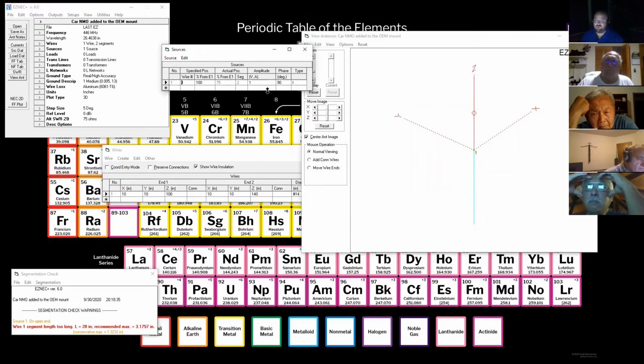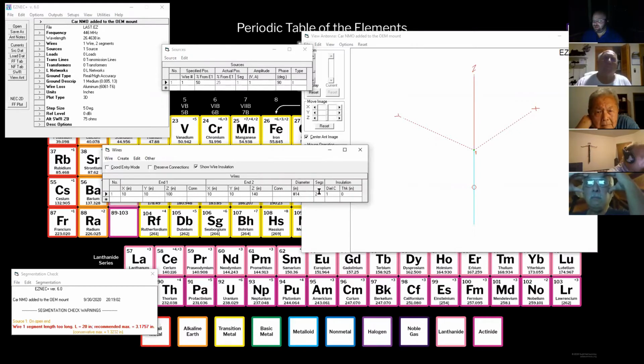I opened an older model. So now I have to deal with the settings I had in the old model. And in that case, I wanted the source out towards the end. But now I don't. So I'm going to say put it right in the middle, 50% of the length. And here it said, well, I can only give you 25%. That's a little weird. So we're going to go figure out why. And that's because I don't have enough segments.